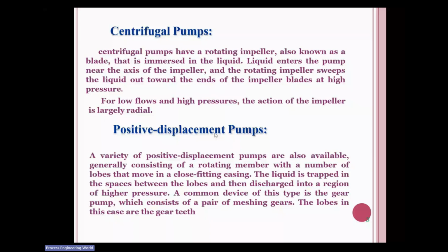That is correct. So what happens actually in centrifugal pumps? In centrifugal pumps also the pressure increases, but up to when? Do you know the term shut off? Shut off head. Right. So if you have closed the discharge valve on the centrifugal pump, what will happen? It will only increase the pressure till the shut off head. But it is not the same with positive displacement pumps. In positive displacement pumps, if the stroke is continuously happening, it will increase the pressure continuously, right?